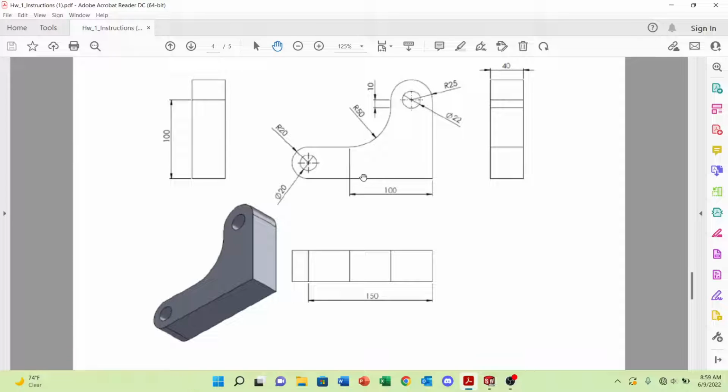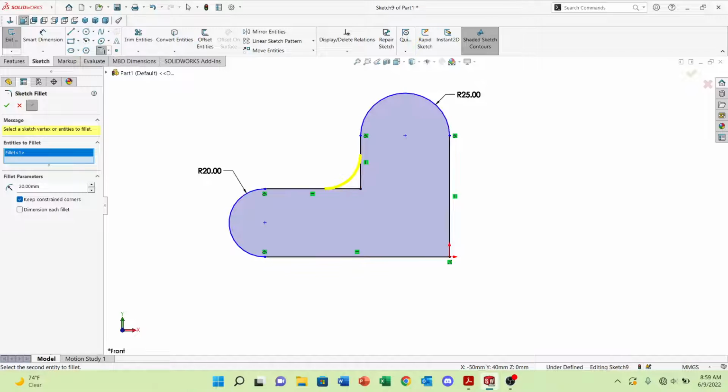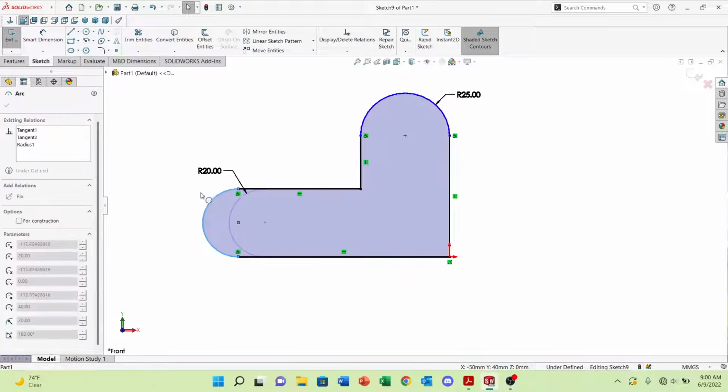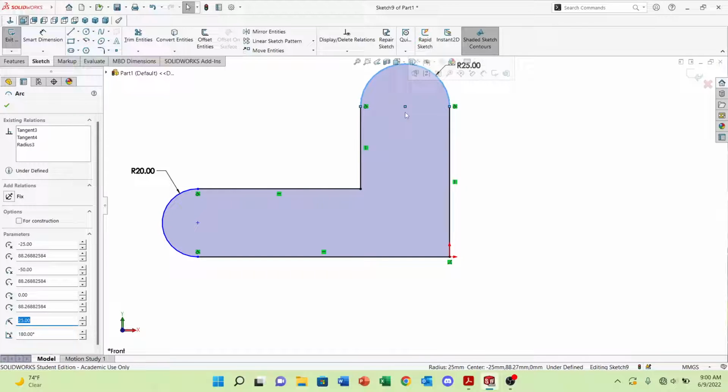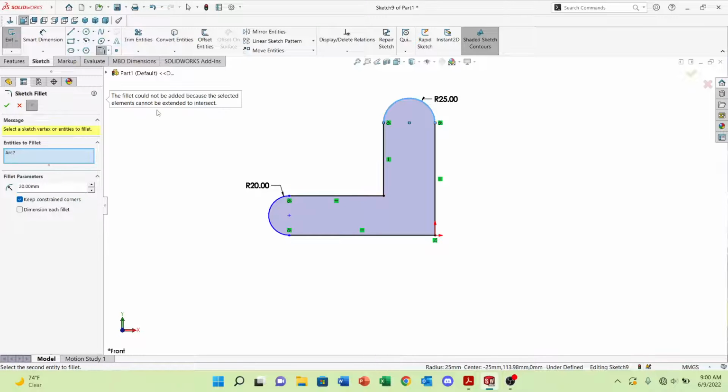Next, this distance right here is 100. So first we're going to make the fillet in that case. So make a fillet. Let's see how big the fillet is. Radius of 50. Alright, so there's not enough room for the fillet, so what we can do is we can stretch this out. The reason that says that is because if the radius is 50, there has to be at least room to make that 50 millimeter fillet. So, oops. Let's make it again. 50. Now there's enough room, you can see. It clearly doesn't go past these two points.